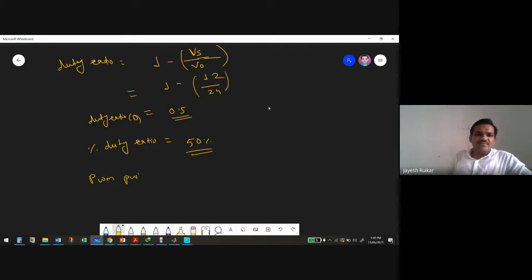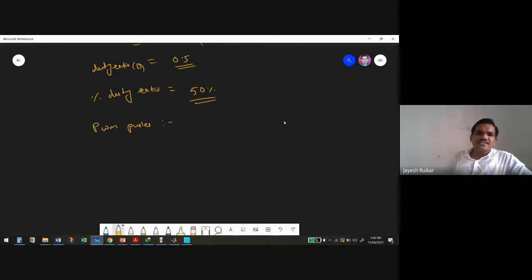Again, we need to calculate the PWM pulse output. What should be the PWM pulse output? As we have already made these calculations, 100% corresponds to 360 degree. So how many degrees for the duty cycle of 50%? It will be calculated as 180 degree. So 50% means 180 degree, and the PWM pulse we need to give is 180 degree. This is what the calculation is.